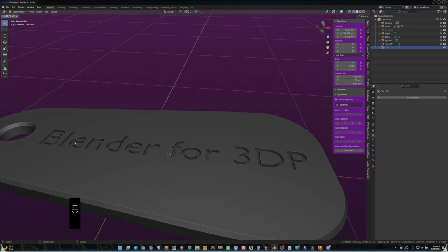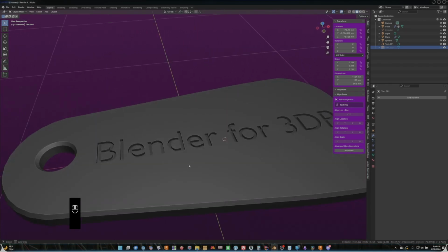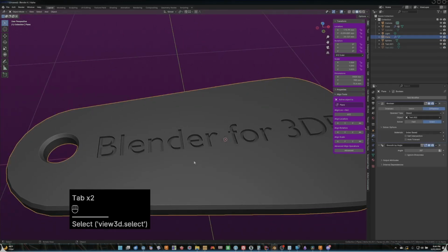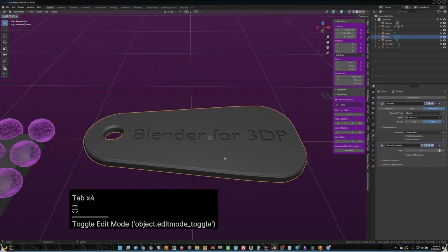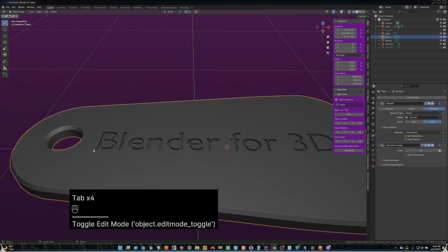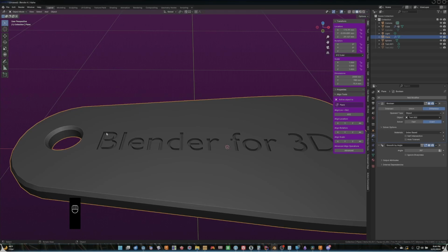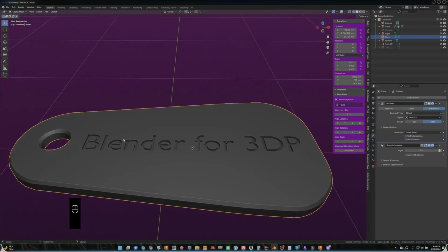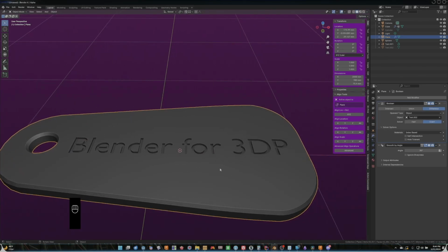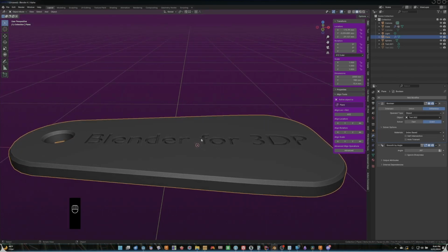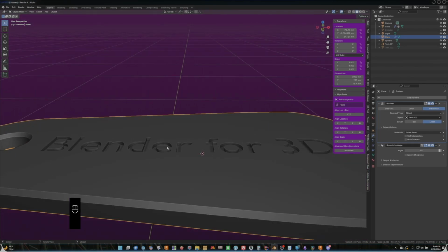Now, if we want to bevel this text, there are options for doing that. Except it's not going to be the bevel you think. It's going to end up being an outer bevel, not an edge bevel. Because the edge bevel, there's too much geometry. You would need to use a paid plugin like Mesh Machine that does a lot of complicated operations to prevent overlaps and give you clean bevels.